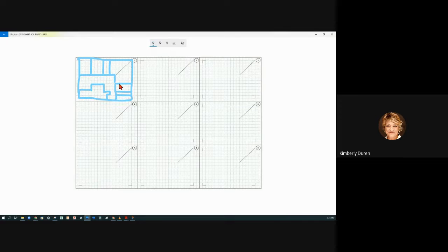So over here, I had a little notch. I need to draw that in. And so this notch, I can project that up and over. And that starts right here and goes across. And it's 1 unit back here. Now you can count the units and draw it, or you can use your miter line.